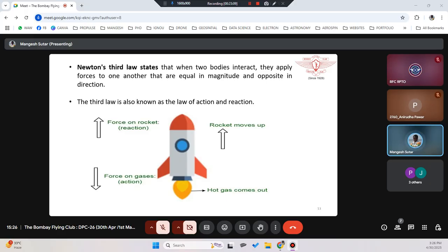Since the wings are designed in such a way, it will glide. The pilot can make the aeroplane glide to a certain extent, kilometers, meaning it can fly up to 10-20 kilometers. It will glide, but because of the weight and since there is no thrust, that means no power, no engine working on it, drag will start acting on it. Drag will try to slow it down. When it slows down, weight will dominate, and then it will start descent. So your aeroplane will start descent. It will keep gliding, and by adjusting a certain angle the pilot will try to make it lift, able to go up and down a little, but not as efficiently as it was able to do with the engines.